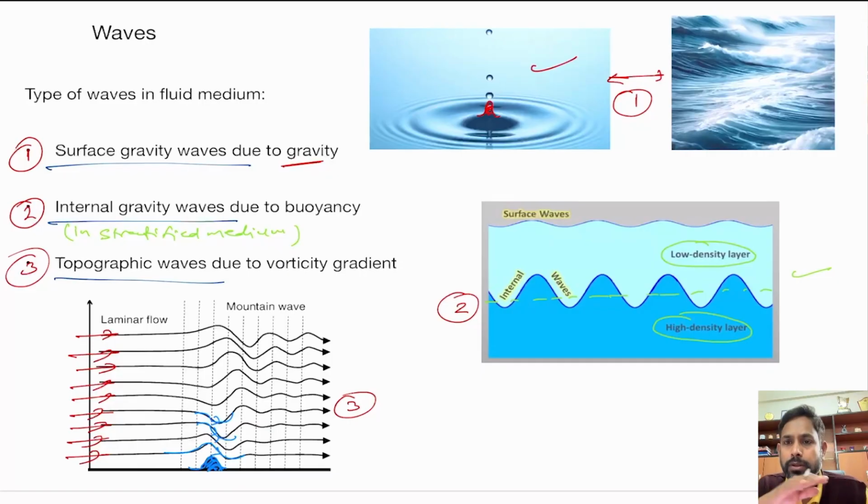Because the flow is not straightforward, now it is getting some sort of circulatory motion because it has to change its direction. So it might be bringing some sort of circulation or vorticity in the motion, and that actually creates this wave motion that you see. Earlier these were all parallel, now we have got this in the form of a wave.